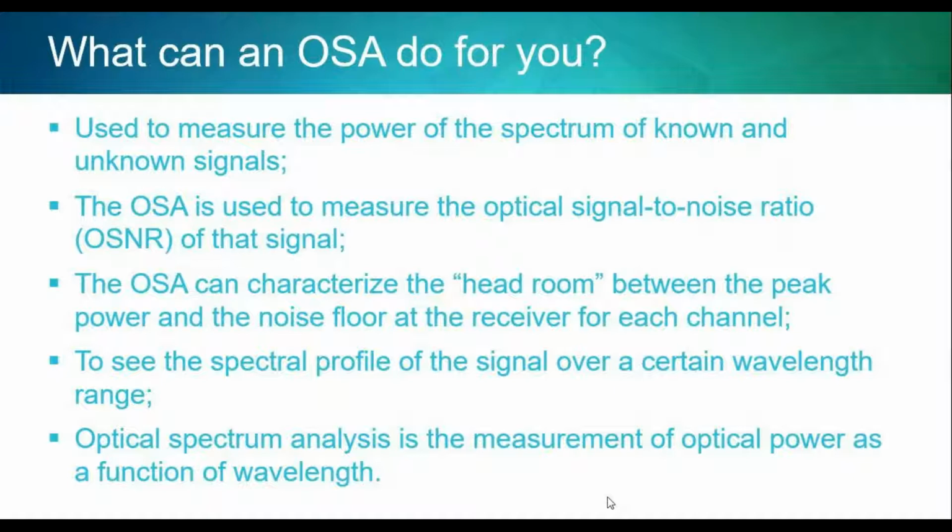on the later slides. So the OSA really is there to give you the whole characteristic of each of the channels, the power, the noise floor, specifically what's required when you're testing at the receiver end. It really gives you what the tolerances of the system are. Okay. Of course, the spectral profile will give you the whole signal over the wavelength range.